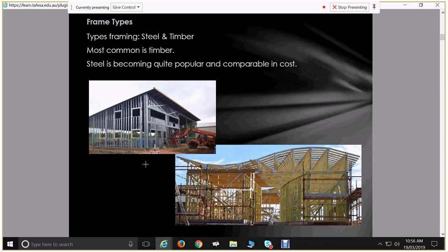Whereas in a timber frame that's built on site, you might have your carpenters just start firing nails in. They're doing it very quickly. They do it every day. They might actually hit a dead knot or something, and that nail goes like this. It doesn't actually provide, and they might not know. That will be your weakest link. And any structure is only as strong as its weakest link. So there's a lot more variability when it comes to timber frames. So just off the top of my head, that's how I look at it. But yeah, I think if you want to go down that path, it's relatively complex.